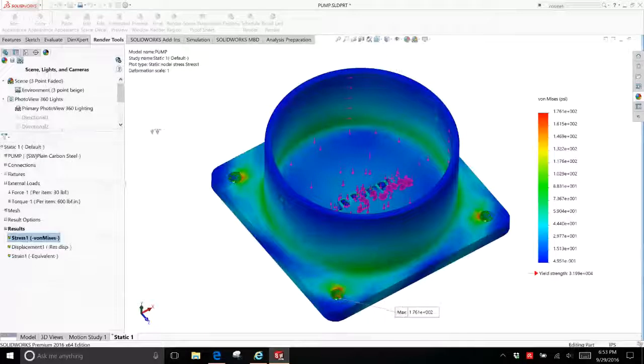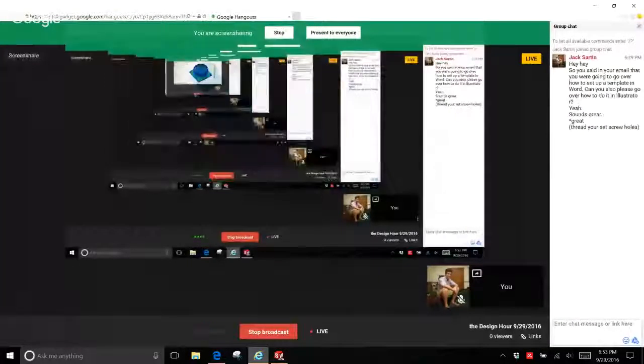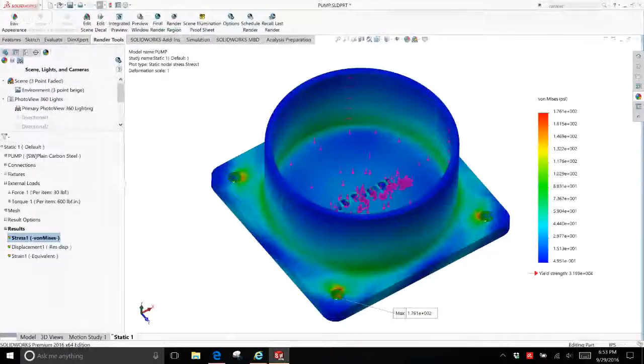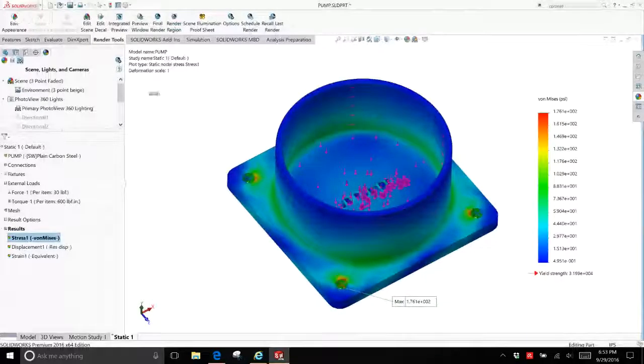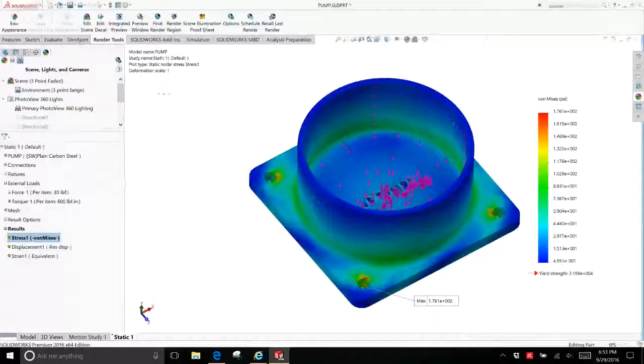This is actually a stress artifact. Because we've set rigid conditions here, the strain in this position gets super high, the stress gets super high, and you get a high von Mises stress accumulation in that spot. And so one of the things that we always want to do is keep the scale. If you're going to report this, of course, you're going to keep the von Mises scale over here. And yield strength of this material is 32,000 PSI. I mean, we're not even anywhere close for this with this carbon steel.